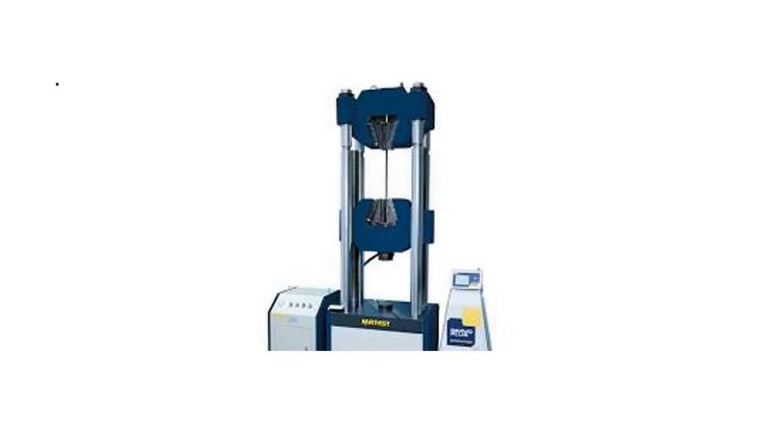It is a small view of the UTM machine, that is, a universal testing machine, in which a standard specimen is placed. Here the standard specimen is placed. There are two jaws. One is a fixed jaw and the second one is a movable jaw. And through that movable jaw, we are applying the tensile load. It may be through hydraulic loading or it may be through servo loading.